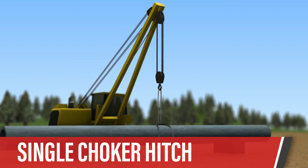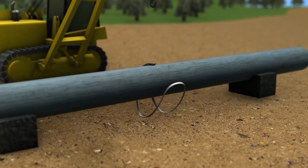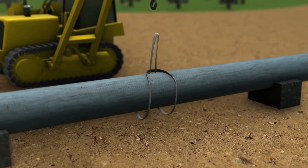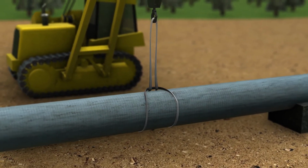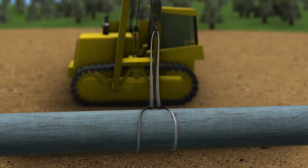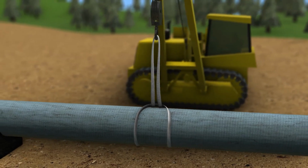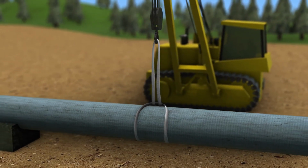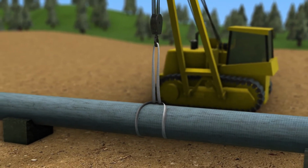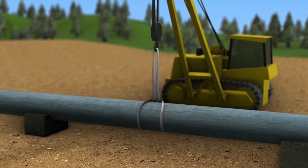Single choker hitch. Unlike the single basket hitch, in which both ends of the sling attach to the hook at the top, the single choker hitch uses a single length of sling material that hooks back on itself directly above the load. The single choker hitch holds the load tighter than a single basket hitch, but will not totally secure a loose load. This hitch is used when handling pipe on hills so that pipe does not slide through the sling.